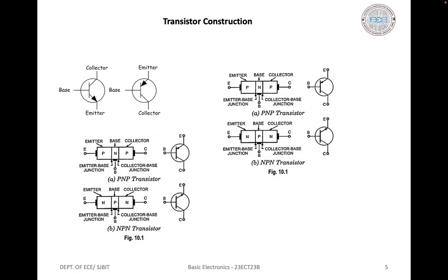Here are two transistor packages, for a low power transistor and a high power device. Low power transistors generally pass currents of around 1 milliampere to 20 milliamperes. Current levels for high power transistors range from 100 milliamperes to several amperes. The high power transistor is designed for mechanical connection to a heat sink in order to prevent the device from overheating. Semiconductor device packages can also be discussed.